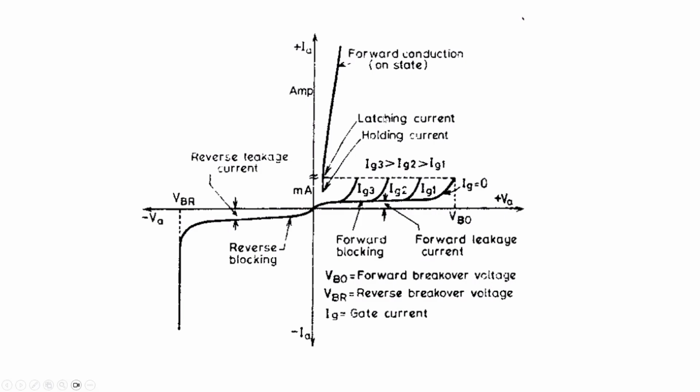Okay, so ITAV, or the maximum average current, is the maximum amount of the mean value of the current that can be flown through the thyristor, and the RMS is related to more of the heating nature of the thyristor. Okay, and here we have two other types of current rating. One is latching current and one is holding current. So as the name suggests, right? So latching and holding. Latching means to latch on something.